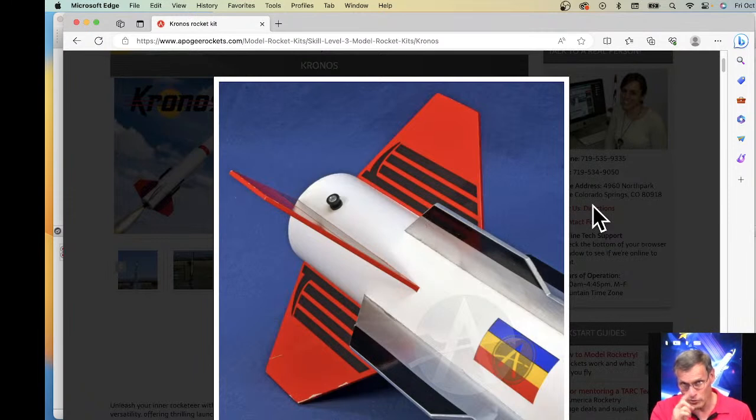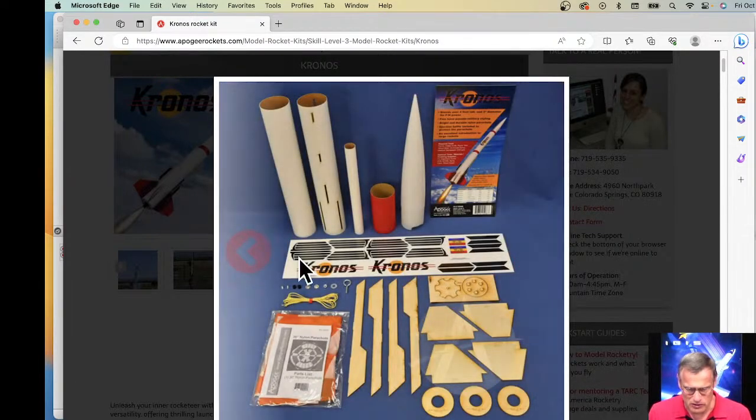And we don't want to do that when we launch the rocket because we don't know which way it's going to go. So that's why we launch it off a rail, because a rail is much stiffer. And so we know which direction it's going to go. So that's why we put rail buttons on this rocket, so that it's nice and sturdy. So when you launch it, it goes in the direction you want it to go. Yeah, so I would recommend keeping it with the rail buttons on it. This is what it looks like when you get it.